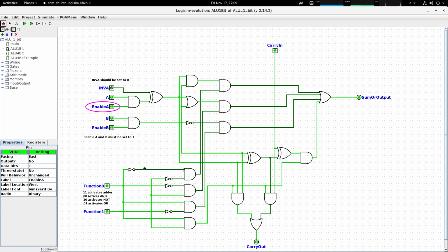And the answer of course resides down here with the decoder part of the circuit. If you look at the decoder, you can see that there are 4 AND gates. Each of these AND gates is connected to a special line which is known as an enable line. So the idea with the decoder is that only one of these AND gates can be switched on at a time. Only one of the emerging enable lines is active at a particular time, and depending on which circuit the enable line is routed to, it will either switch on the outputs of the full adder, or switch on the outputs of these three Boolean logic circuits up here.